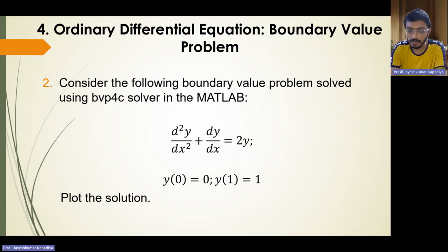So till now what we covered, we first looked at nonlinear equations that we solved using fsolve, fzero and the roots command for polynomials. Then we looked at linear equations. For that we used the linsolve MATLAB inbuilt function, and if the inverse of the matrix is defined, then we can also use inverse of A into B, or we can use A backslash B. Further, for ordinary differential equation initial value problems, we used ode45, ode23 or ode15s as solver.